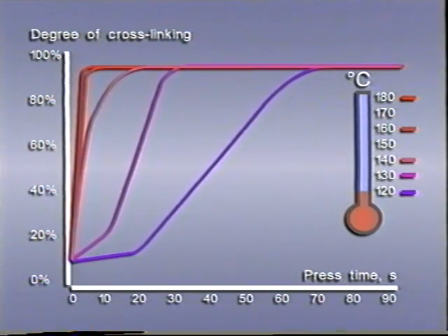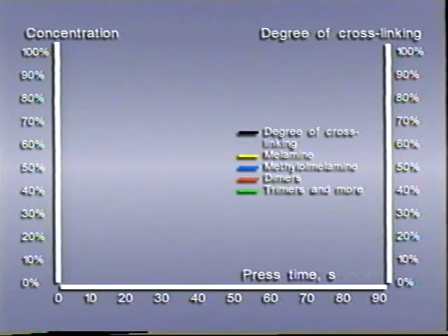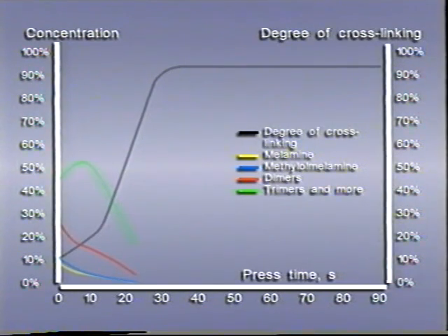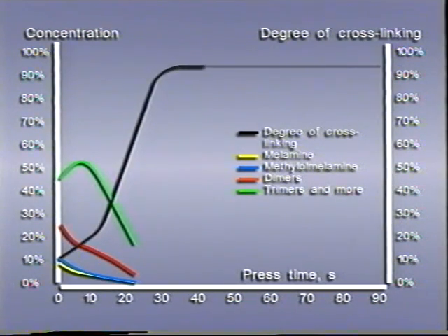By examining the molecular changes, we clearly can distinguish between the flow and hardening phases. Initially, the portion of the oligomers, here displayed in green, rises rapidly, but it soon recedes, giving way to cross-linked molecules. This maximum level marks the transition from a liquid resin to a thermoset.